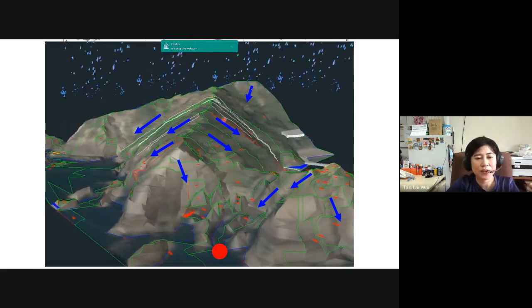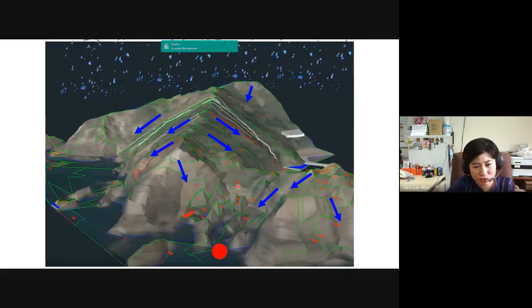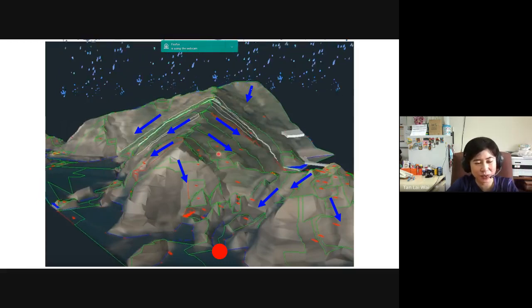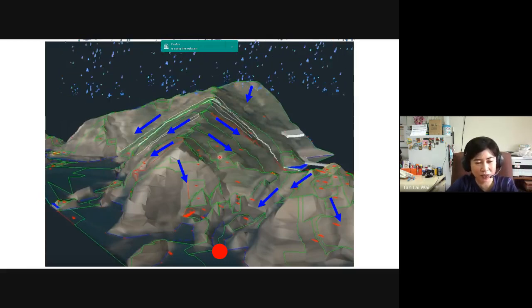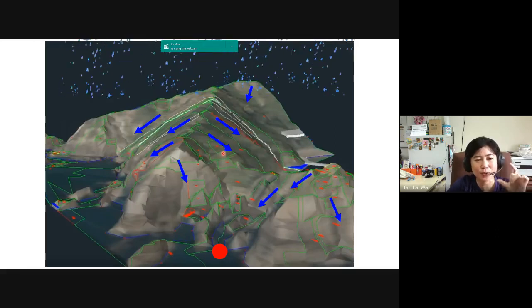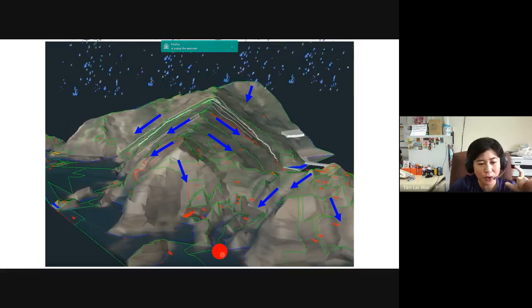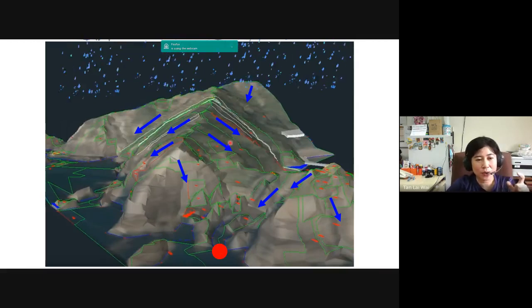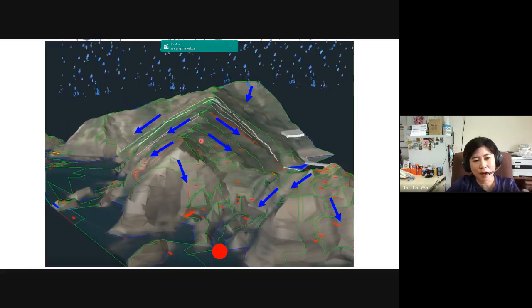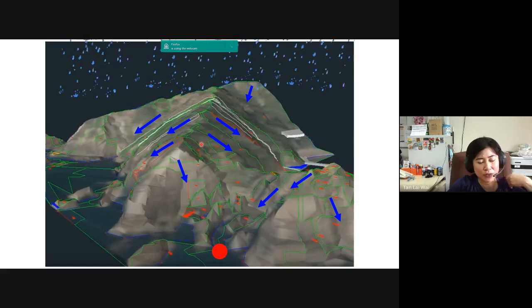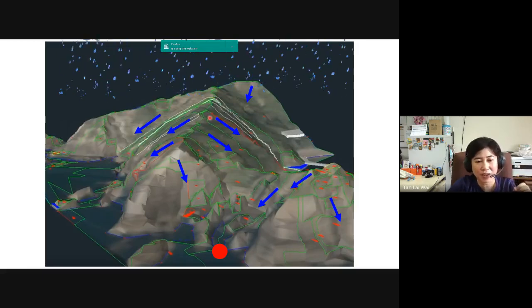But if there is some interception due to seepage, or you have depressions where the rainfall runoff is stored, then your C would be smaller. Therefore, your Q would be smaller than I times A. If you look at the Manual Saliran Mesra Alam, or the Urban Stormwater Management Manual, C depends on land use.